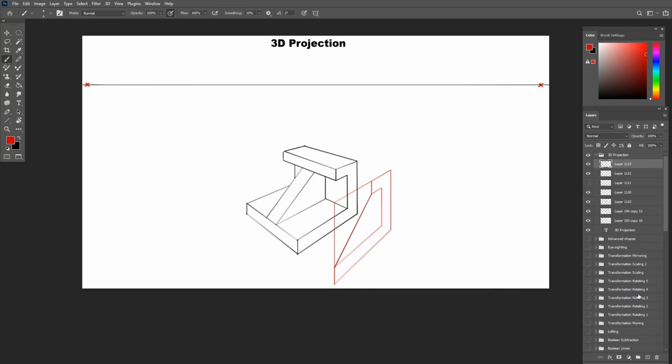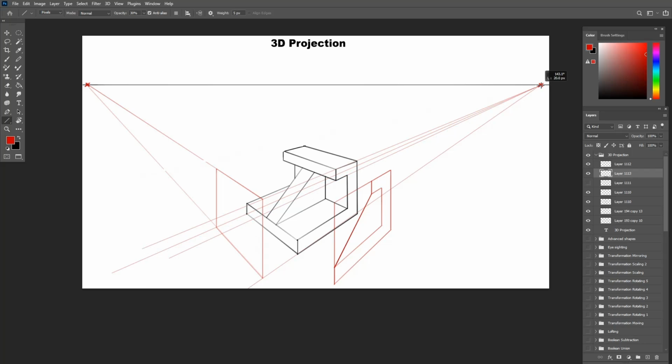Let's now do the side view in the same way. First projecting the whole bounding rectangle for the entire shape. Then we add the details inside, starting with the top ledge and the bottom platform. Finally adding the slope in between, which will look like a rectangle in this view.